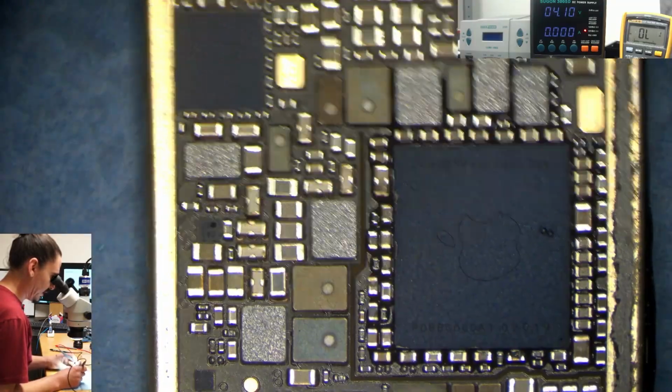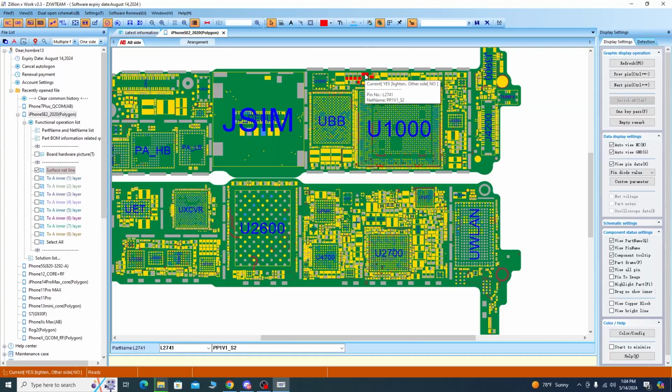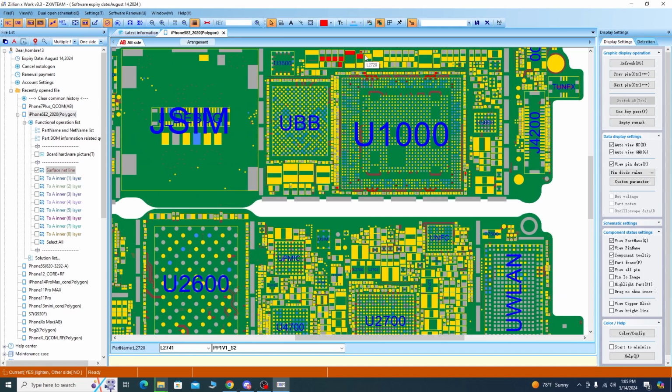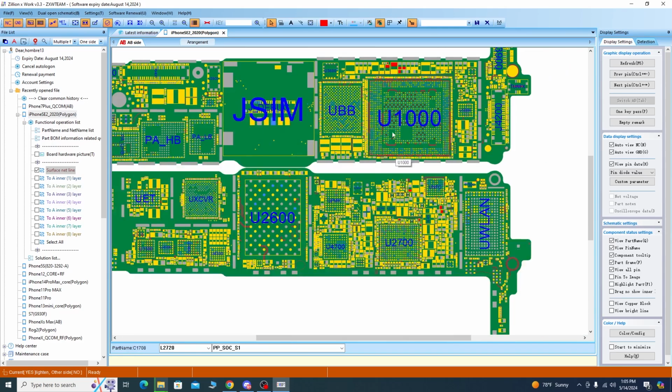So yeah, I should check the RAM lines now. It's also going to be worth it to check these coils that are around the CPU. I haven't checked that, as we can see. So I have this fourth capacitor here. PP sock I need to check over here. 1V8 is the RAM line.